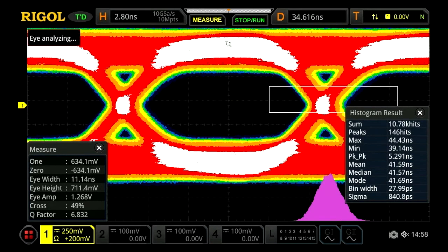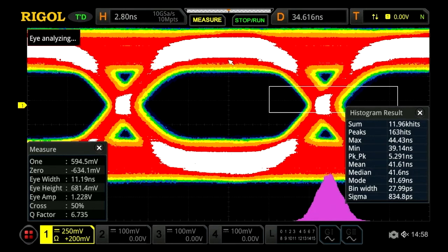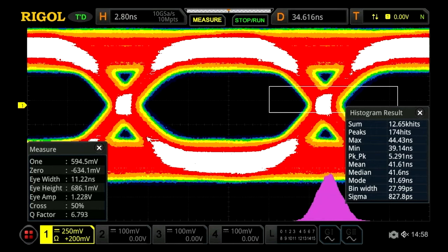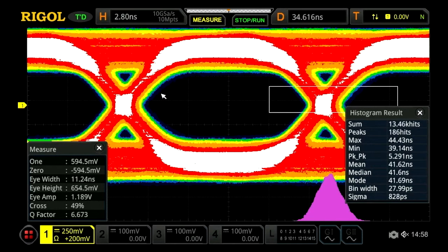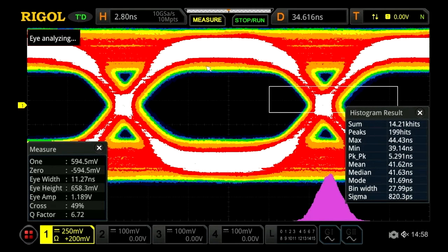One, we see vertically a lot of space here. This implies a certain amount of noise coming through the signal that might be affecting our ability to get a clear bit test at this point. Additionally, the rise and fall times on these transitions are pretty diagonal, at about 45 degrees. In these settings, we'd like it to be steeper, giving us clearer corners in this eye diagram. That's likely a bandwidth issue, not allowing the signal to change fast enough.